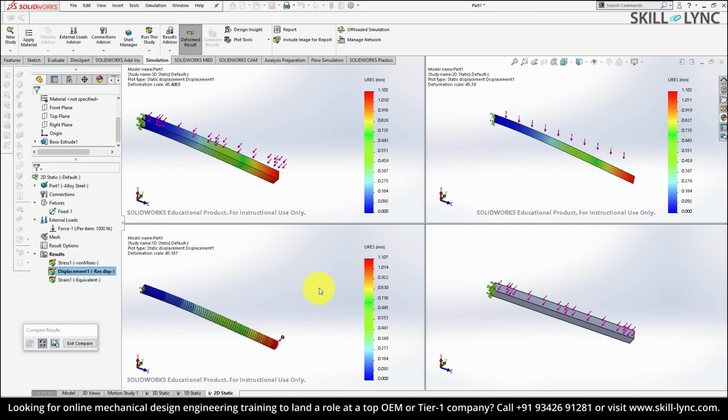for a particular part. For example, if you have a part in which you have lengthy members and you are only concerned about the bending stresses in those lengthy members, then you can very well consider the member as a 2D element or a 1D element to avoid computational complications. So instead of going for a 3D model wherein you have a lot of elements, you can consider it as a 2D shell element or even a 1D element and look at the displacements and the stresses developed.